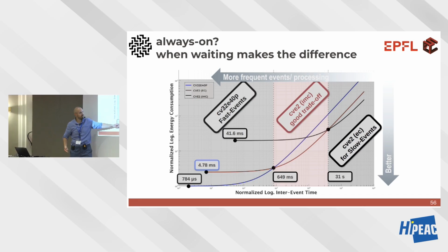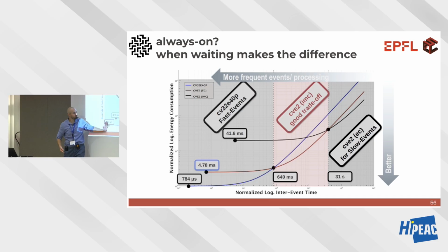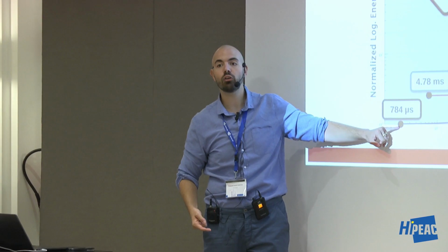It's true that it finished later. You see it finished here. And the black dots are the graph before. So this is 6 times. See, if you do this, it's 6 times faster. And the energy is worse, because you see it's more energy. So it finished later and consumed more energy. Fantastic. Now I'm waiting. This guy is increasing leakage much faster than the other. And so, in this specific case, at 650 milliseconds, the second CPU becomes better.